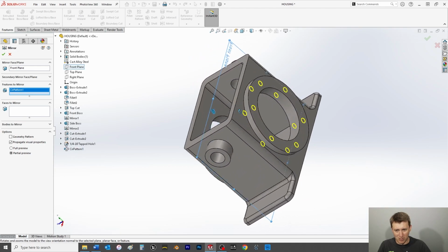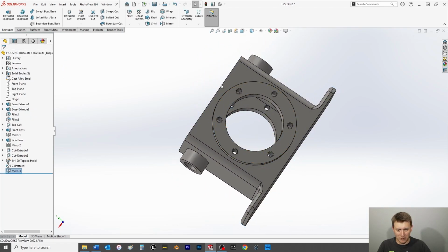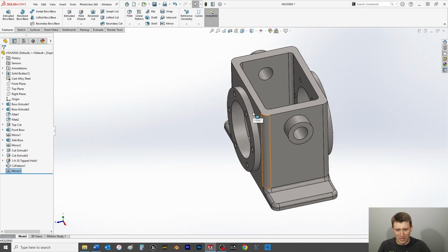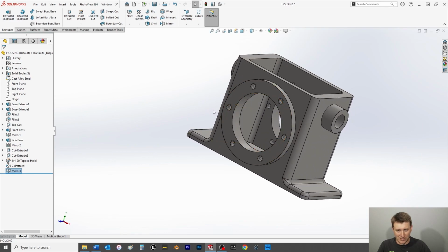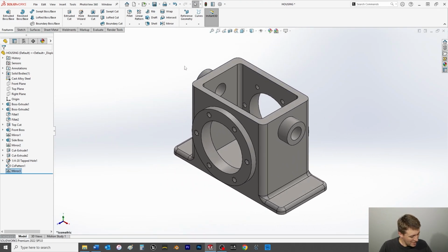And look at this partial preview we're getting here. And now I'll click OK to finish it out. And just like that, we have threaded holes on both flanges. So I'm going to hit the space bar, go isometric, and that finishes on page 90, just before section 2.54.